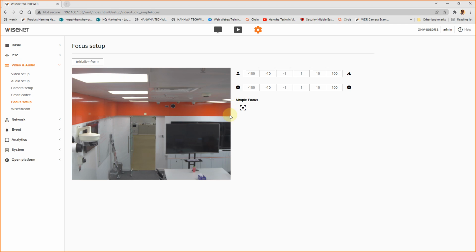All right. So this is a varifocal lens, standard varifocal lens. Why is it usually 2.8 to 10 or 3 to 10 or 2.8 to 12? This is the reason, you can take a thumb rule. Every mm is like 1 meter blind spot. So if you start at 10, you are losing 10-meter coverage. No one will buy a camera and put it in the corridor and start after 10 meters because that's a waste of money.